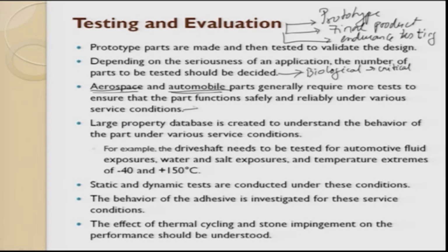So the service conditions for aerospace are minus 50 degrees C to plus 50 degrees C, and it has to work. Whereas when you talk about automobile, it generally works between, you can take it from 0, very rarely on minus, up to 50 degrees C. Maybe this can go up to 50 degrees C, because that is the atmospheric temperature we have, and sometimes it can be tested even at minus 10 degrees Celsius, to see whether the engine components work, the spark plug cranks, all these things can be done. So these are the service conditions, and it can be altitude also.